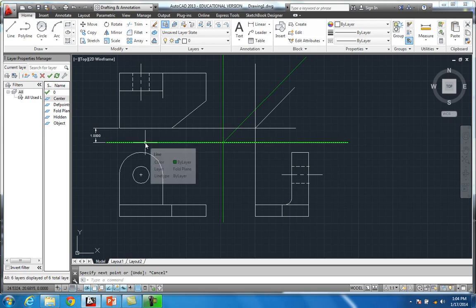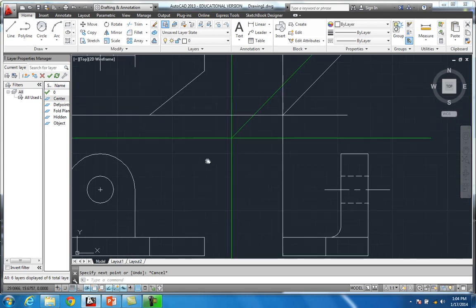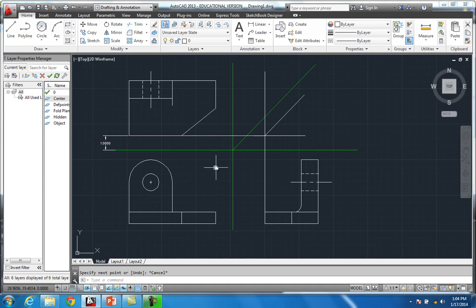Everything will be exactly to scale and to shape. However, if you want to be accurate with the glass box theory, these have to be projected according to the size of that glass box. Okay? So this right here, inside this plane, is the glass box for the front, and the top and right side go along with it. So we need to make this right side view correct. We need to bring it over 1 inch and start it, just like how we did this one. You all see that? 1 inch up. I would just recommend offset 1 inch off that fold plane.